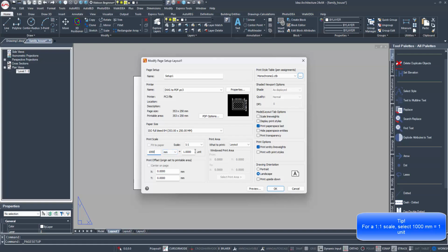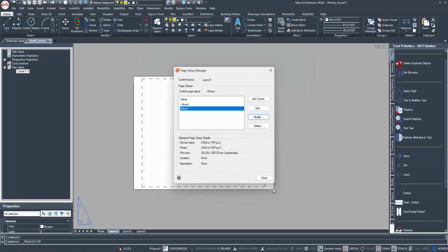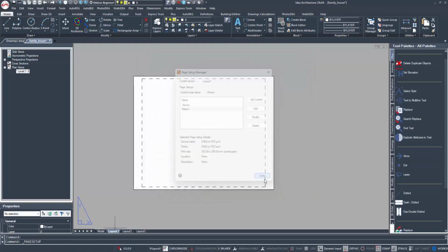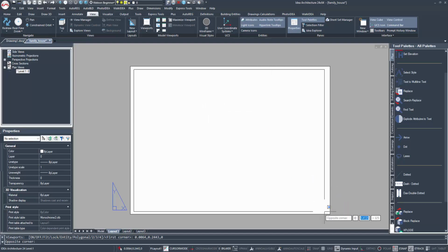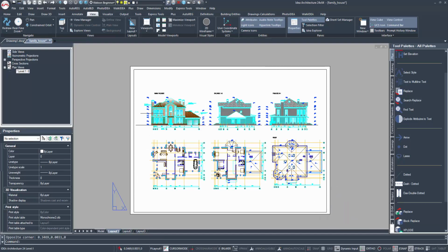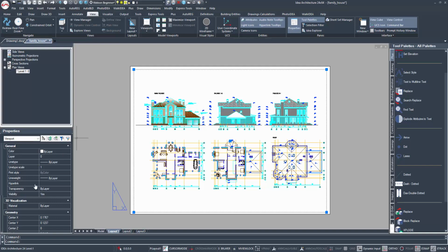After completing the setup process and saving the settings, we notice that the reference sheet has been adjusted to the size we specified. Next, I insert a viewport within the new boundaries, and by selecting the viewport, I can apply the desired scale, for example, 1:100.